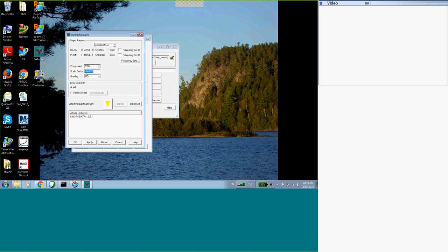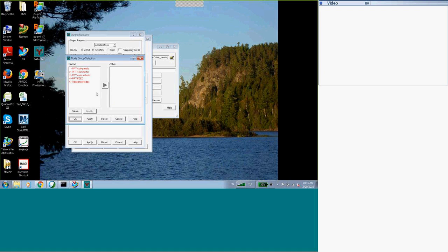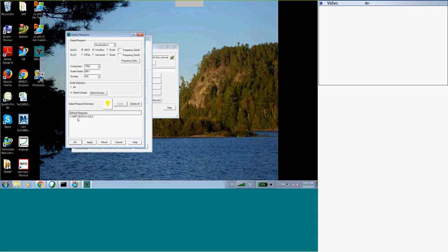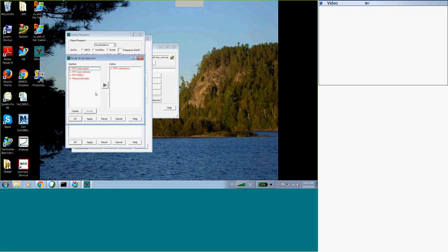I'm going to have rotational components. I'm going to put a scale factor here, make it interesting. And I'm going to select subreflector here for this demo. Then I'm going to have some acceleration plots. So what I'm going to do is turn these guys off and set 2. I'm going to ask for data in all formats, HTML page. I'm going to create a scale factor.